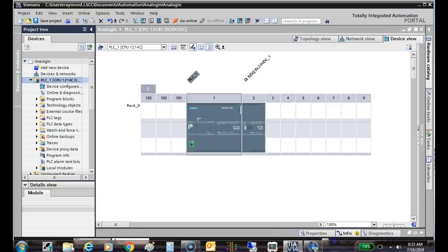Basically the way it works is they set the A to D converter to a reference voltage, and then they generate a linear line. And then they switch it over to the input unknown, and then they start a counter counting. And they count until it crosses 0, and when it crosses 0, that's the actual count.